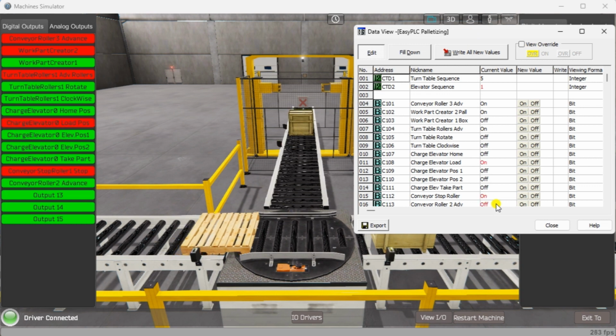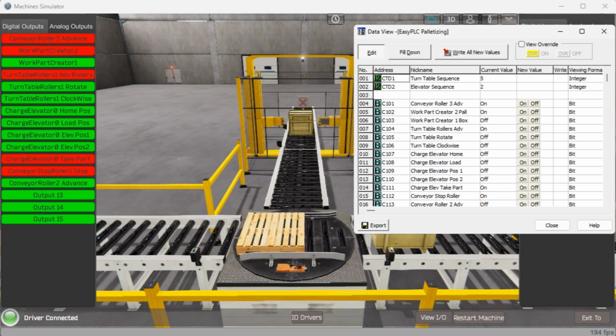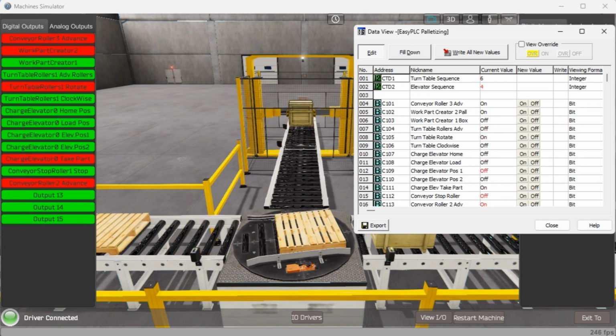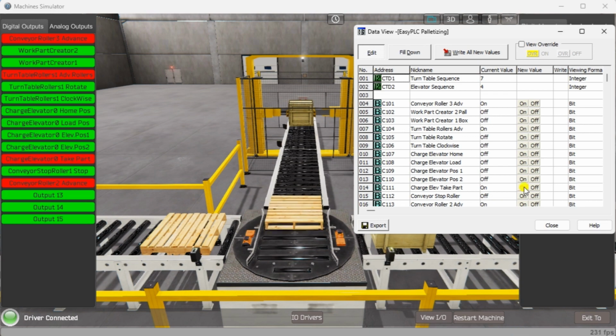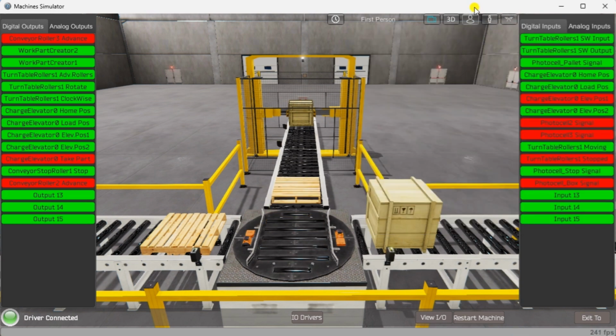Using Machine Simulator MS to test the program will ensure that our program works. Troubleshooting is quickly done without damage to any physical hardware. You can practice your modification and debug by modifying the palletizing operation in the following way.